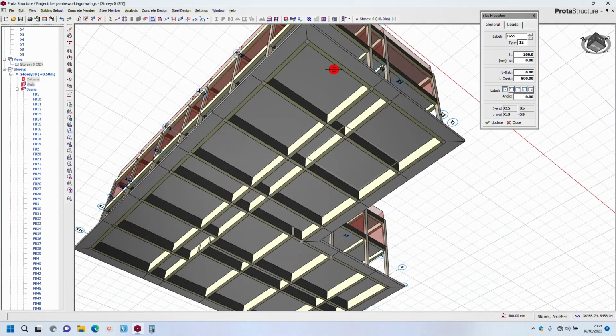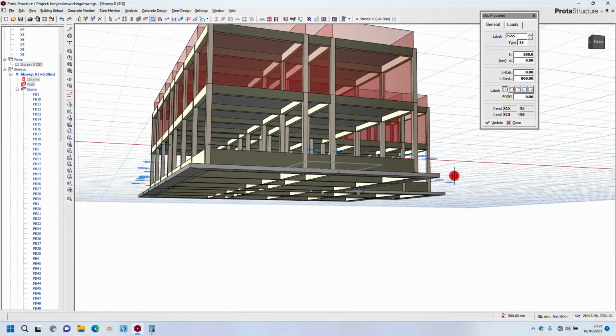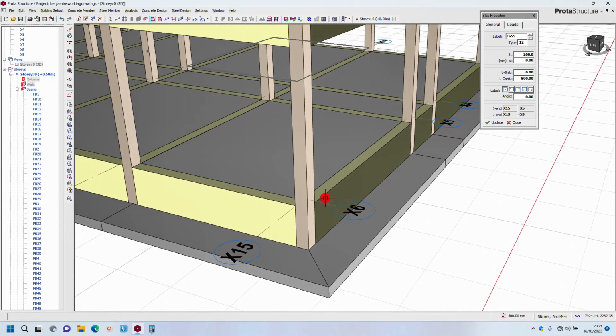Now this place is going to be backfill before the slab, and the pressure that is trying to pull this wall apart is going to be high. So this slab toe helps prevent that from happening, because from the detail, the reinforcement of this wall and this toe is going to be connected to each other. So it's just going to be something like this. So it will be difficult for this thing to twist when this slab toe is here supporting it.